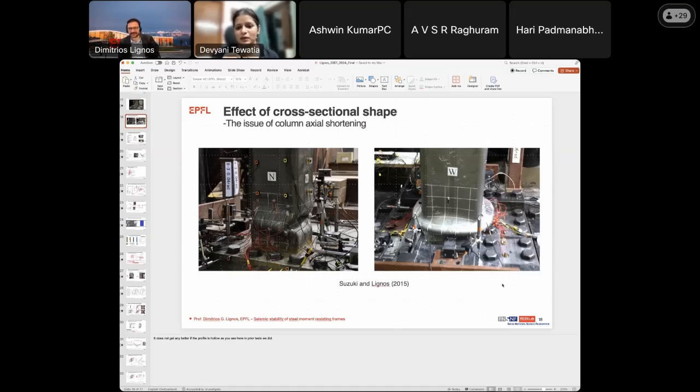The next question is, would your recommendations for web slenderness and axial demand-to-capacity ratio hold true for short frames, like 1 or 2 stories, when the structural sizes are gravity dominated, as in a data center? These recommendations would mostly apply to the first story columns. Technically, we don't have any limit on the number of stories, but for a 2-story or 3-story building it is generally harder to get close to these limits.